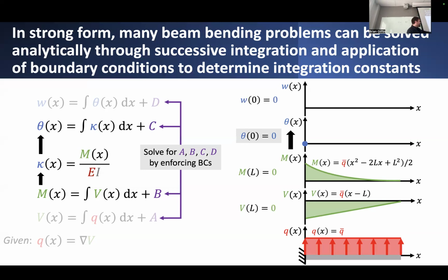If, let's say, EI was really a tensor, if you recall, in that case, if I had maybe 2 bending moments, bending about X and bending about Y, or whatever the 2 transverse directions are, to invert this relationship, I should really be inverting this 2x2 matrix or this tensor in order to figure out what are the resulting components of curvature with respect to the different axes. So there might be some interaction. Some moments about X and Y might generate some interacting bending curvature about opposing axes.